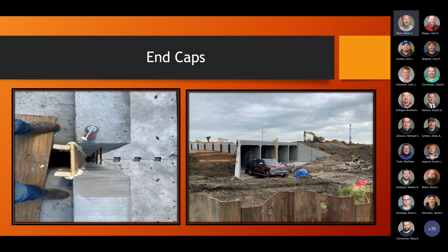They then went and attached plywood and braces across the opening on the outside every foot and drilled 4 concrete screws per brace and said they were ready to pour. I suggested putting more angle bracing into the approach slab slots to get better support with all the concrete, but they said it would hold. I was right. After getting 3/4 of the way full, the forms started to blow out and they quickly started putting the angle forms in to brace better.